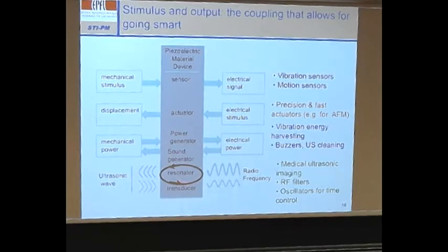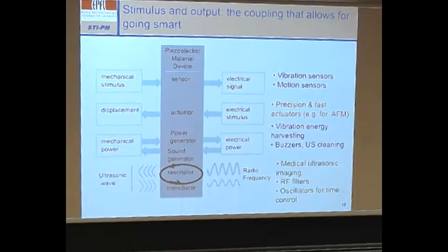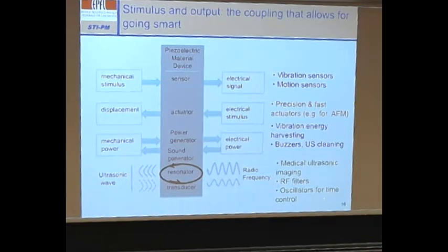And then we have transducers which go in both directions, so it's required that you go in both directions. This gives nice resonators and transducers. Medical ultrasound imaging is about 3-5 megahertz to look through the body, and 10-20 megahertz to look into the eye or artery walls. So that's at least RF filters I'm speaking of.